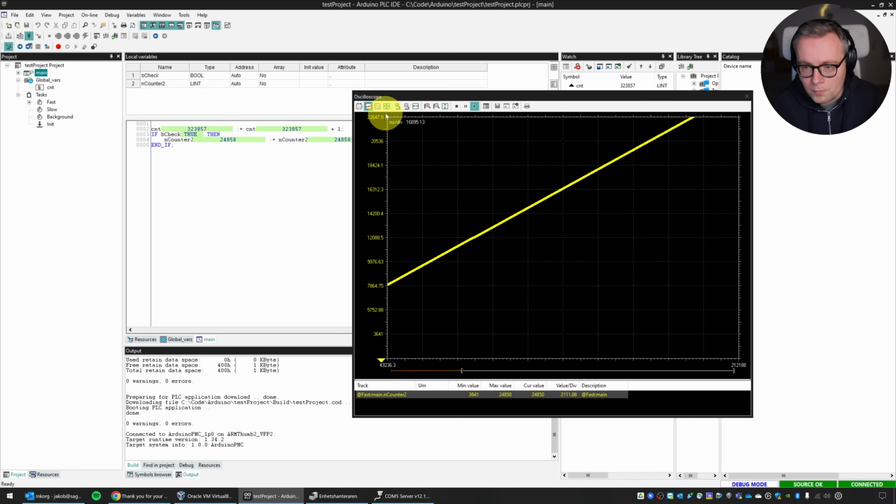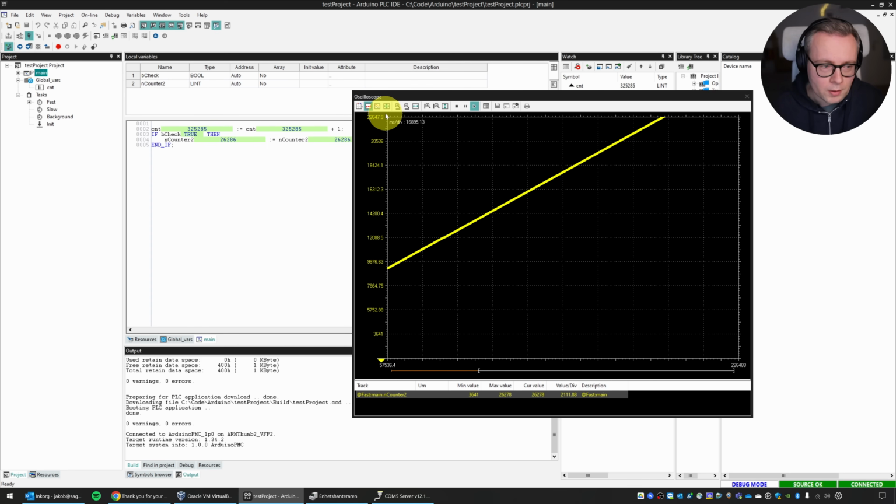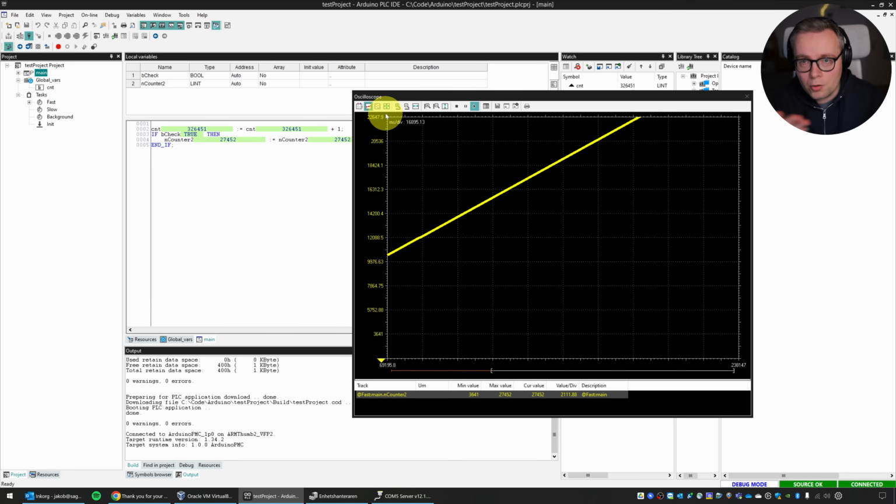That's the important question. The immediate feedback I can give to Arduino, and which I really hope they change, is the whole thing with source control. Don't store it in the way that you're doing it now for the structured text part. Please put it into separate files and don't do any annoying XML markup. Just store it in pure text. This is gonna pay off, because then me and other people can use our normal version control tools that we're used to, and that we're even using for your other IDEs, to store all the source code and do diffs and work with that, and integrate it into our build pipelines and everything that we're gonna want to do in the future.